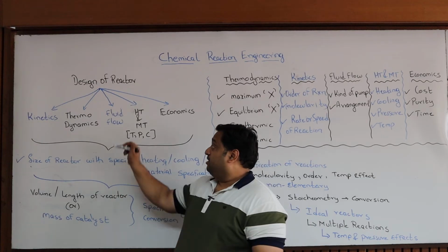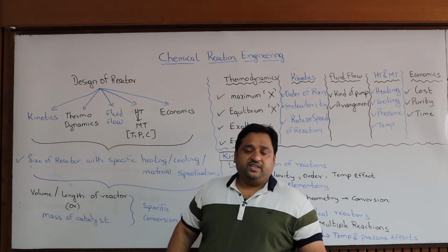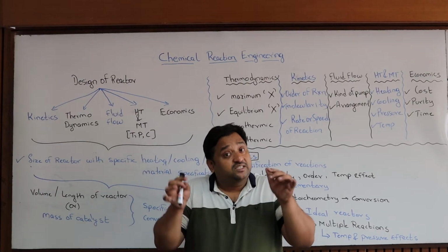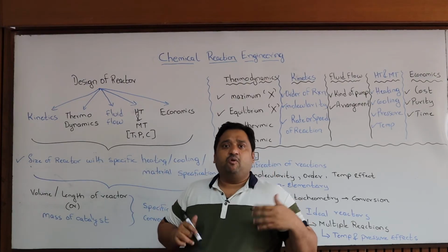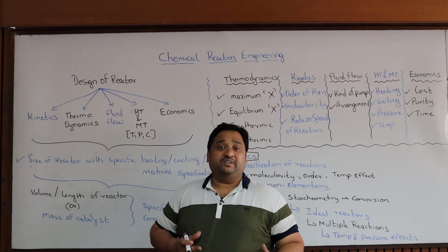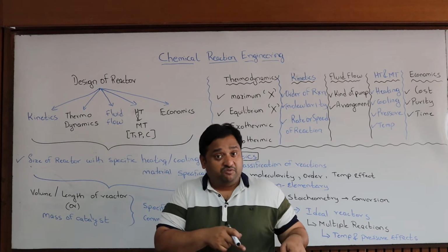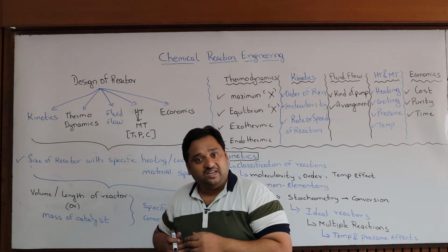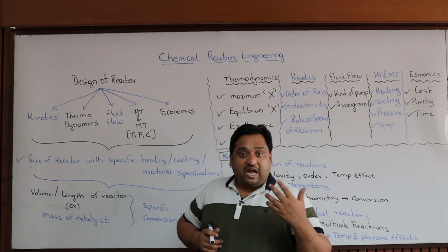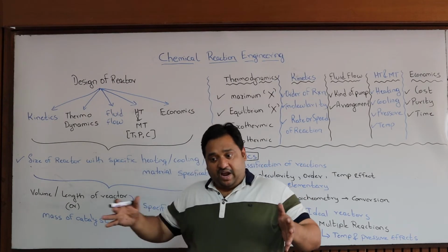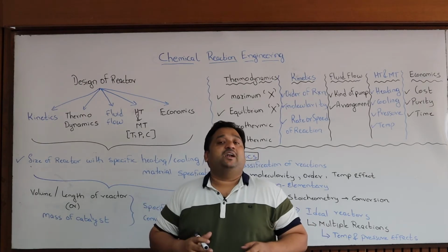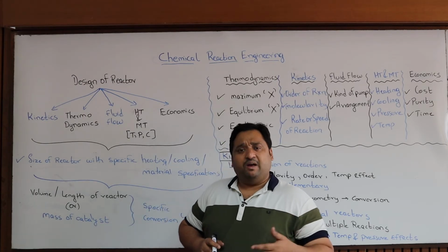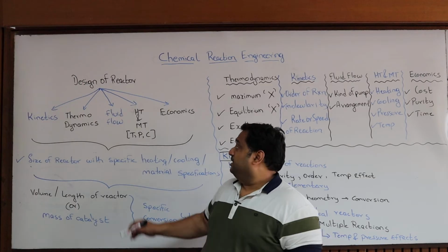Okay? Fluid flow. If it is a certain reaction, if it is a liquid consisting of solids, what kind of pump are we going to use? Is it appropriate to use a centrifugal pump or a reciprocating pump, or is it a viscous liquid or non-viscous liquid? Depending upon the kind of feed or the kind of liquid or gaseous system we are dealing with, we have to go for the design of a compressor or a pump.